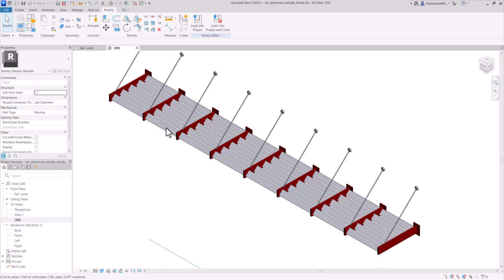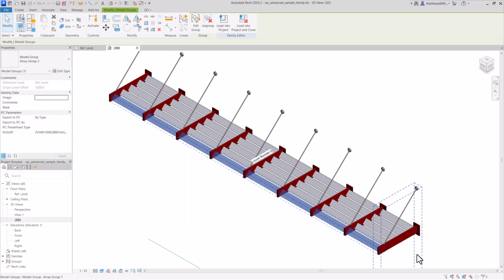One of the things I want to point out right away is that the geometry that's getting imported, we want to make sure that it represents our intentions for actually building this structure, because that's what's going to be reflected in Inspire or SimSolid or wherever this model ends up. One example where it might not represent our intentions is these longitudinal slats. We can see that they are continuous along their entire length, even though in reality they would have to pass through this transverse cantilever somehow. Or perhaps they're broken up between each of these cantilevers, but that's not reflected in the geometry at the moment.